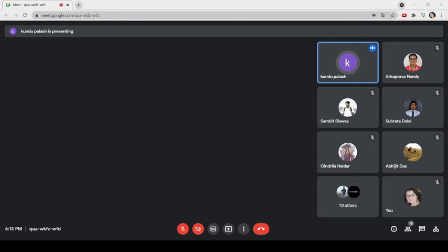So how will it work? First of all, there is another control register associated with the two timers, called the TMOD register, which can set the mode of operation of the timers. The relative bits have a physical significance: M0, M1, C/T and GATE. These 4 bits are associated with timer 0, and the upper 4 bits, the upper nibble, are associated with timer 1. That is the architecture.